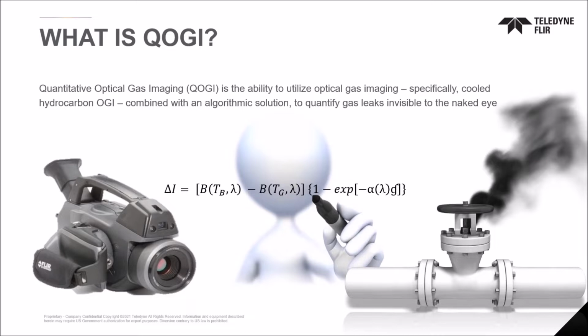But in essence, that algorithm that you see right there is not just a bunch of numbers and letters. That is the actual algorithm that Providence Photonics, who is our partner in this venture, that the QL320 uses inside of it to be able to quantify the leaks. Now, there's a lot going on inside there, and there's a number of variables built into that algorithm, but that's actually what is happening inside the camera. The delta I there is the change in intensity at a pixel level as that pixel moves across your screen.